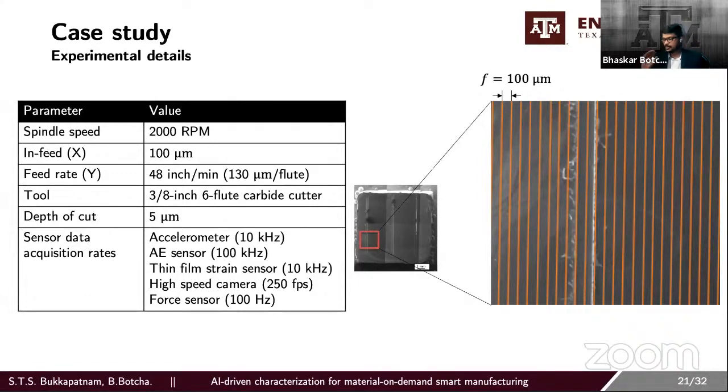The spatiotemporal resolution which I'm showing you here is the initial milling cut, which happens with the 3/8-inch milling cutter throughout the whole sample. In this particular case study, we still haven't looked at the micromill samples. Right now, this data set refers to the 3/8-inch cutter, where I'm finishing off the sample right after I establish a datum with my cutter.